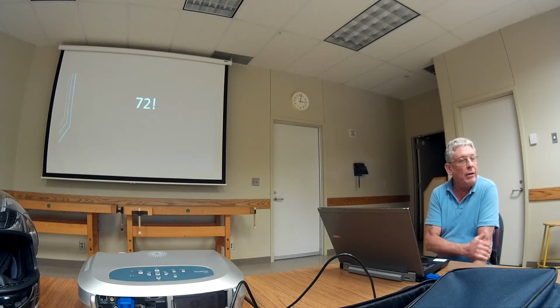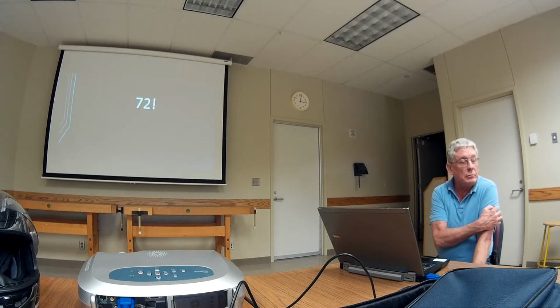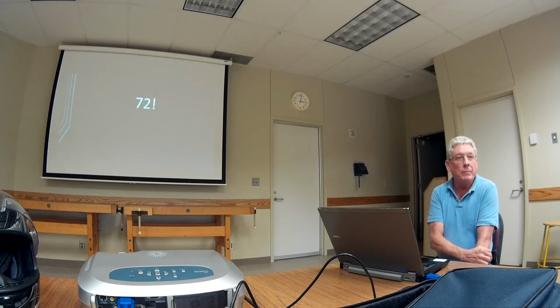It's pretty close. I could look at different stages, how much gain I was expecting out of this op amp and this, and I added them together and got exactly what the simulation gave. I have 105 dB of gain in the audio section, and that's just about exactly what the thing told me. I happen to have the right parts. I happen to have the op amp model for it, so I was able to plug it in there and put the rest of the pieces through with some assumptions. I think that's the other thing, models have gotten a lot better. LTspice is free and it's incredibly good. Good support, try it.